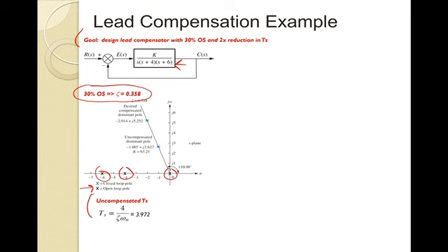For a gain of 63.2, I'm not showing you the root locus, but the 0 and the -4 would come together and go off axis, and the -6 goes off to infinity to the left.